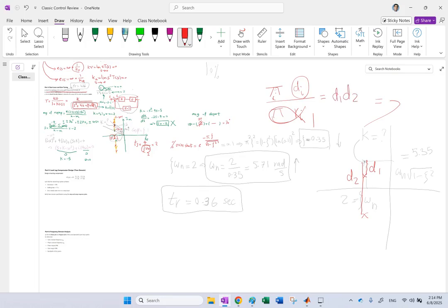So if you find the distance from this point to the original two poles, which were at -2 plus minus j, that should be your gain. How much is it? Well, their x's are all the same. The y's are different. One distance is to the 1, one distance is to the -1. So one of these is 5.35 minus 1, which is 4.35, and the other one is 5.35 plus 1, which is 6.35. So if you multiply these two numbers together, that should be the gain at that location.